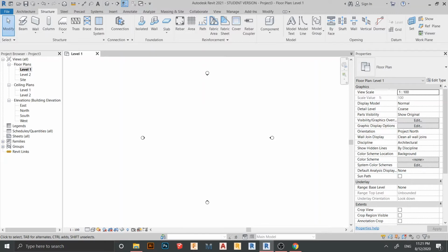Okay, so now I am in the Revit interface. We're using the architecture template in this project. Now I'm at level 1. Before placing my structure, I need to create grid lines and place columns and beams first. After that I create the roof by footprint, and only after that I place my steel structure using beam system. Okay, so to create our grid line,